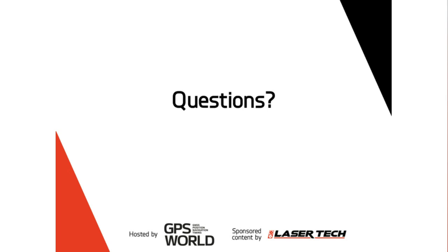Okay, thank you. All right, and do you have to calibrate the compass in the TruePulse 360 models for azimuth accuracy? Yeah, I can take that question. We do have user field calibration routines on our units, especially with the compass. Steve did talk about that magnetic interference at times that could affect the compass accuracy. And so we do recommend when you get to a site, it's about a 30-second routine to calibrate the compass. We want to make sure you maintain that azimuth accuracy.